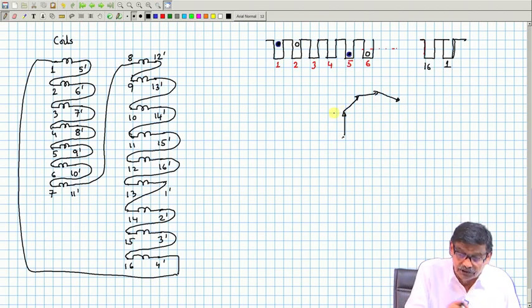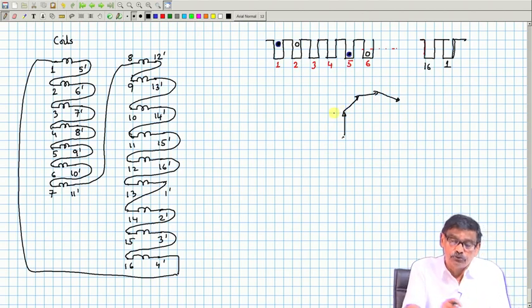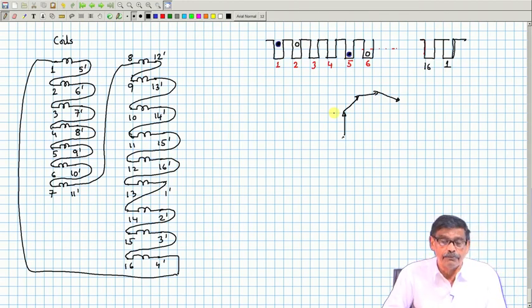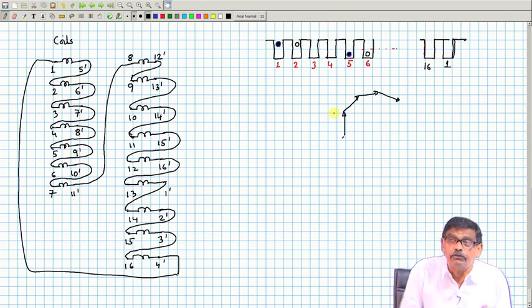Therefore, the resultant voltage acting in this closed coil, each one of which is a seat of EMF, the sum of the induced voltages will become 0. So, we need not fear there will be a circulating current, although I know pretty well that each one of them has become a seat of EMF.